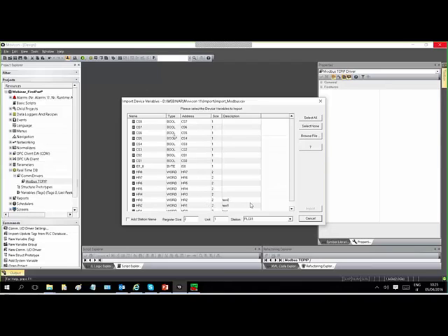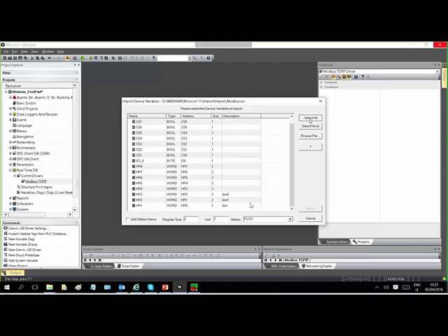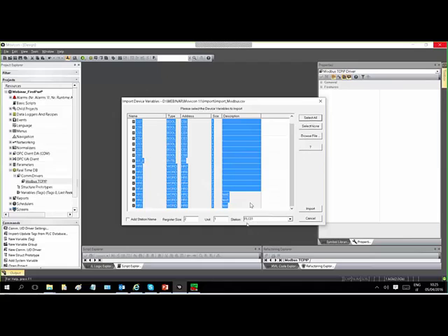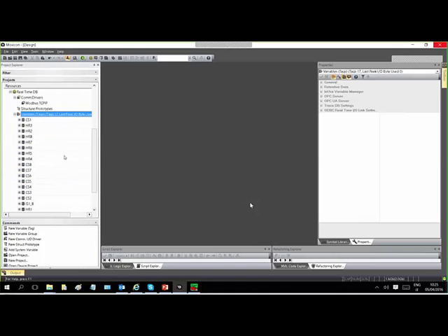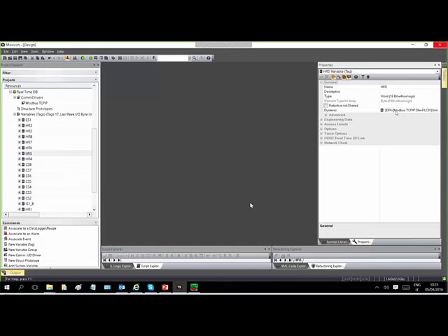I just prepare a CSV, select all, address these tags with the IP address of my station, import. Finished. So, a few seconds. Here I have my whole list of the tags that are already linked with the PLC, because the dynamic task is built automatically. This is the standard point of communication between the tag and the PLC.